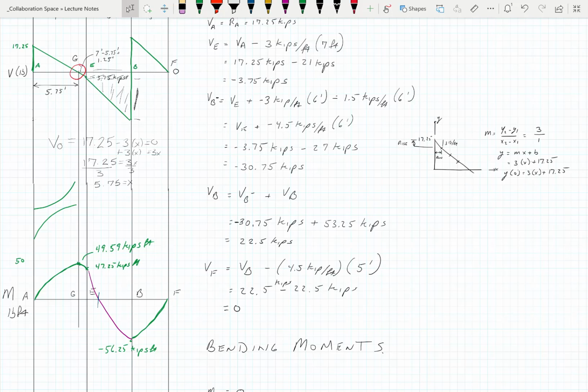So if we take a negative 56.25 and we take a look at the stress that goes with that one, you're going to carry that negative with it, times the C, so the centroid of the part, the shape, divided by its I value, correct? Which way is that going to go? Smile up or frown?